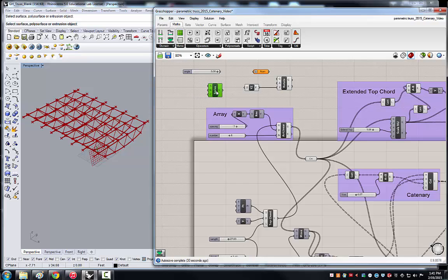And for that, we want to put in a number and a number of steps, right? So the series, the n for the series is the step size, which is our angle. Each step will be 5 or 4 or 3 degrees. So that's our step size, goes in there. And then below that in C, it wants the number of values in the series, and that's going to be the same as the number of trusses, and it will change as we adjust our array.